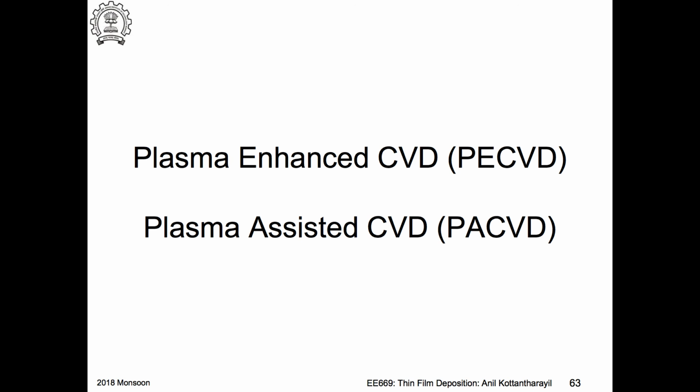Can you guess what could be the reason? Yes. Okay. So yeah, what she is saying is that once you make your source drain and make the contact, let's say you have nickel silicide there. Okay. So can I go for high temperature deposition of anything on top? Okay. So you can't do this.